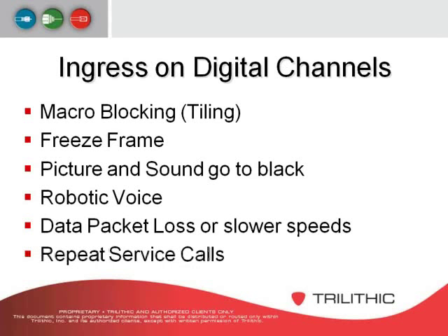Now digital has a different effect. You'll see when there's ingress there, macroblocking, freeze framing, picture and sound can go to a black screen, robotic voice, data packet loss or slower speeds for your high-speed data, and repeat service calls.